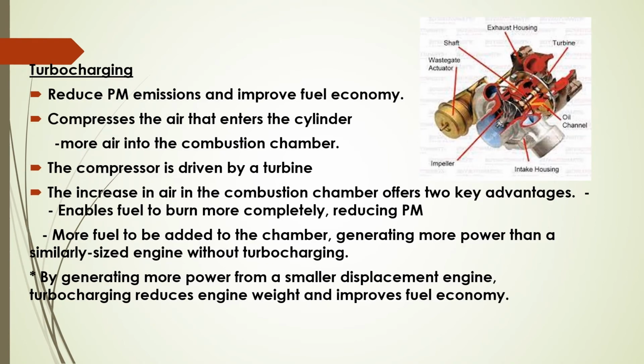Lastly, the turbocharging. Turbocharging can both reduce the PM emissions and improve the fuel economy. A turbocharger will compress the air that enters the cylinder and will cause more air into the combustion chamber, and the compression will be driven by a turbine, which in turn is powered by the engine's own exhaust.